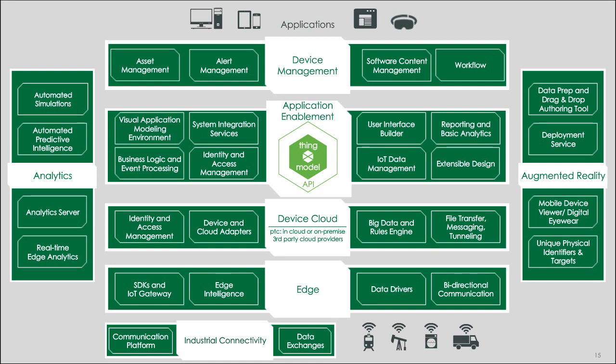Kepware is an industrial connectivity suite that creates protocol drivers to connect directly to industrial equipment, whether it be Siemens equipment, GE equipment, Mitsubishi equipment. The list goes on and on. I believe there's about 160 different drivers for many different pieces of equipment, and it is able to extract the data in its native form and aggregate it at a server level and feed it into our Thing model, which I'll talk about in just a second.